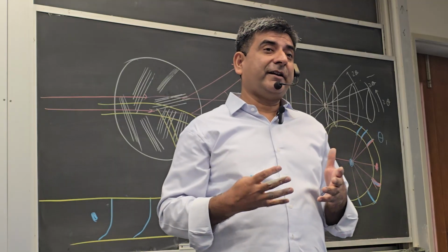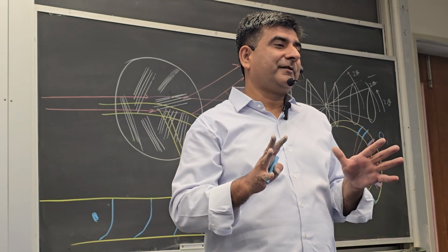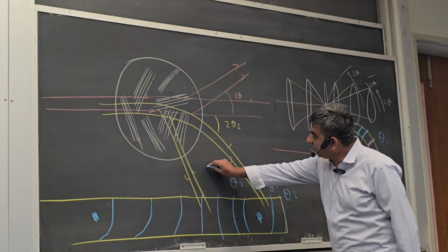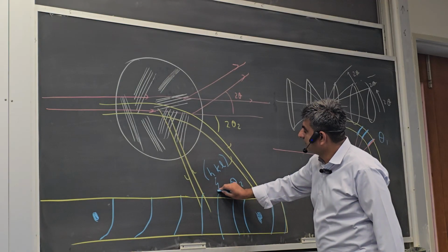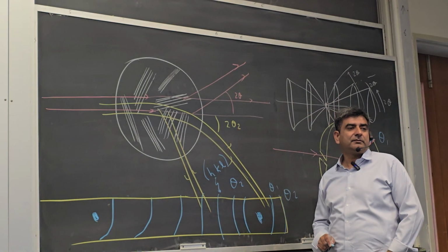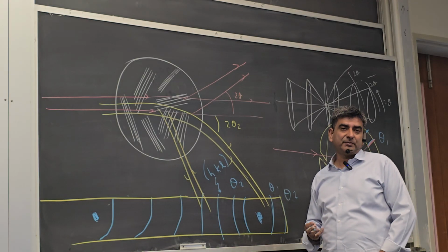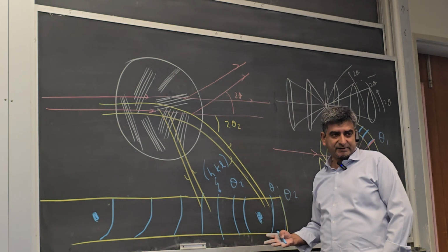If you know, say, it's cubic, then you can associate a plane HKL with each one of these diffraction rings. And of course you can tell the lattice spacing a from this as well. So I'll show you some examples of this in our next class.